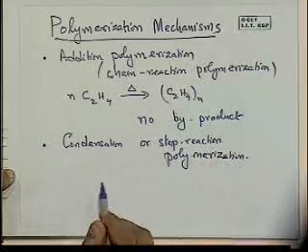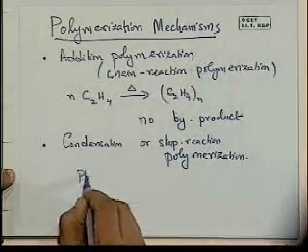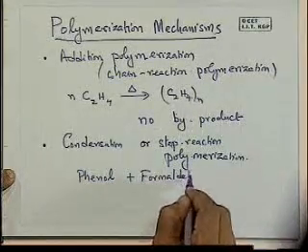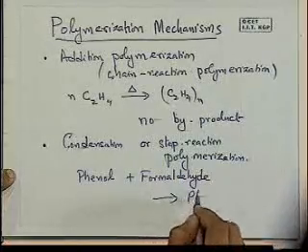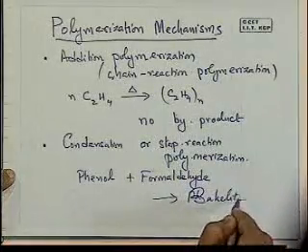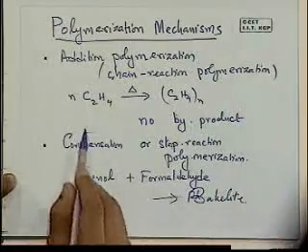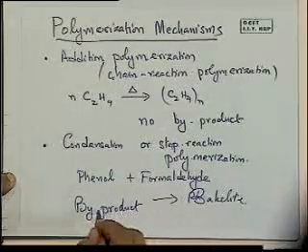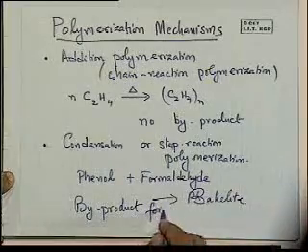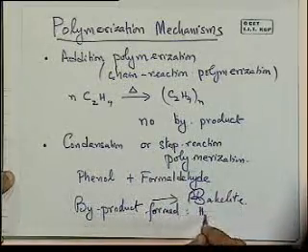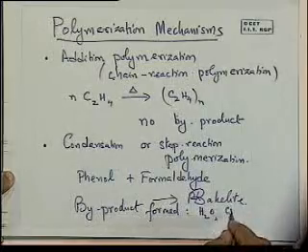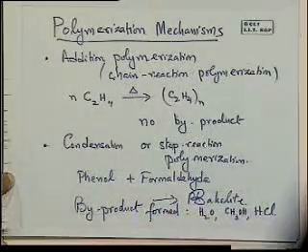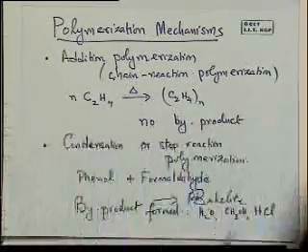And we already looked at this example of phenol formaldehyde formation, and I'll give that a little more in detail here. The important difference between condensation and addition polymerization is that here we have some byproduct formation. The byproduct could be a water molecule, methanol, HCl, etc. Some byproduct is formed when we combine two of these together.